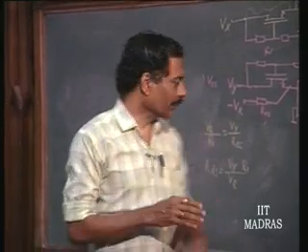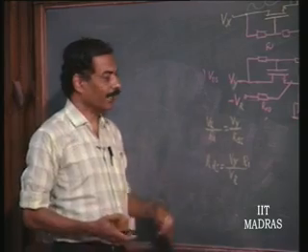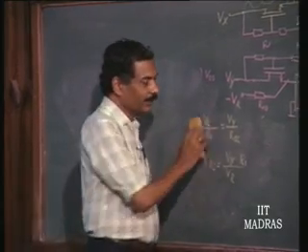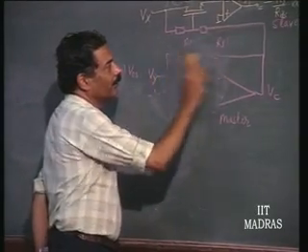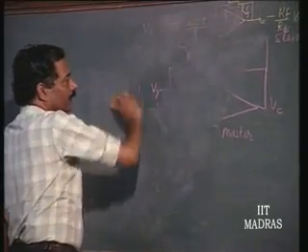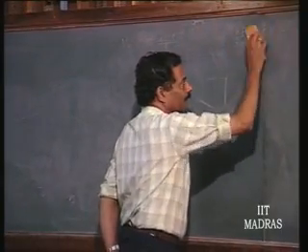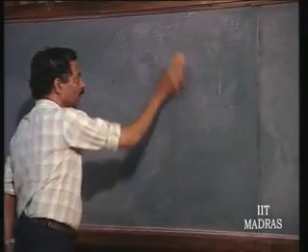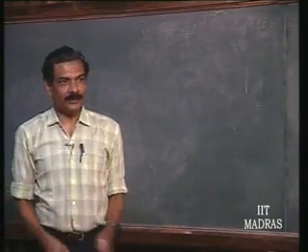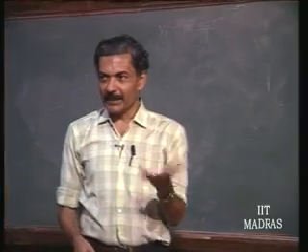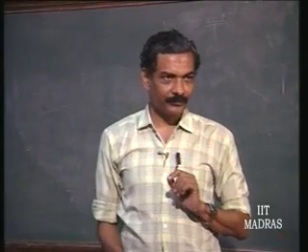Is this clear? So, this is another technique of designing multipliers, particularly popular in regular laboratories, where you can use two matched FETs to design a fairly good multiplier. This is not 4 quadrant, what is this? This is 2 quadrant, because Vx can take on both polarities, Vy can take on only one polarity.